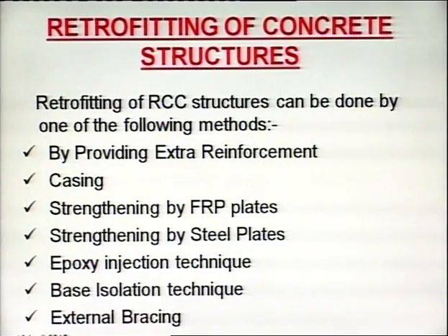Then we have seen the epoxy injection technique. In these techniques, the minor cracks are filled up with low viscosity epoxies, and the major, wider cracks are filled up with high viscosity epoxies. Then we have seen the base isolation technique, a very important one.